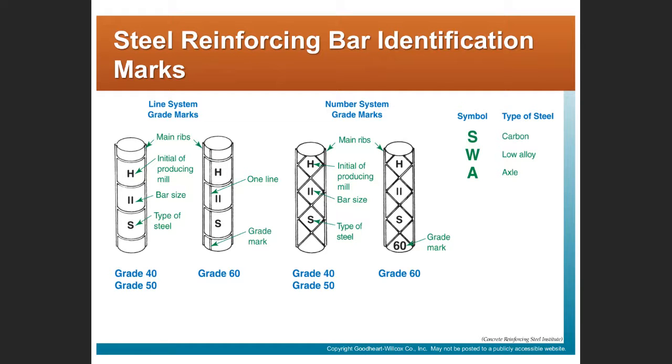I'm not that terribly familiar with this, but just like any other steel product, the type and grade of that product will be indicated on the rebar. So the drawings or specifications, depending on the strength that they're looking for, may call for a specific type of steel of a specific grade. Remember way back when we looked at those couple of YouTubes about how they make steel? Remember, steel is iron with other stuff thrown in to give it specific properties. So if we're looking for specific properties in the steel, that will be called out in our drawings and specifications, in our construction documents.